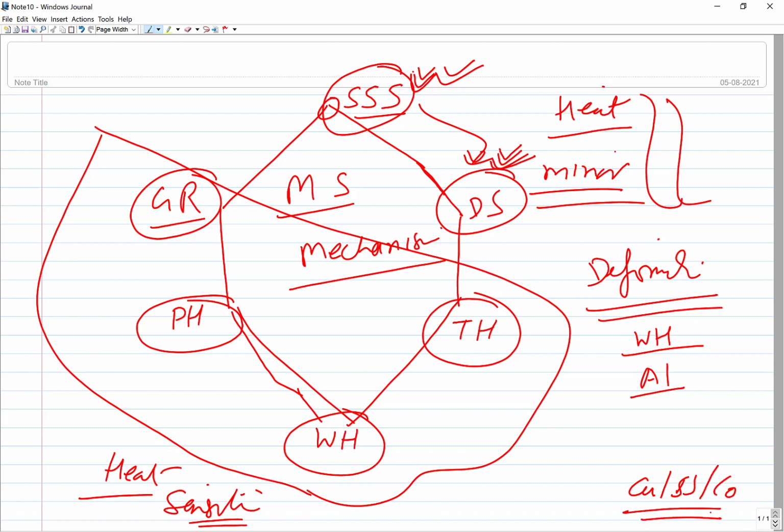So there are a few work hardening metals, designed for that. On the other hand, a few metals may show very weak work hardening behavior. So the way a metal gets strengthened due to deformation, due to work hardening and strain hardening, will significantly dictate the response of a particular metal to the solid state joining process.